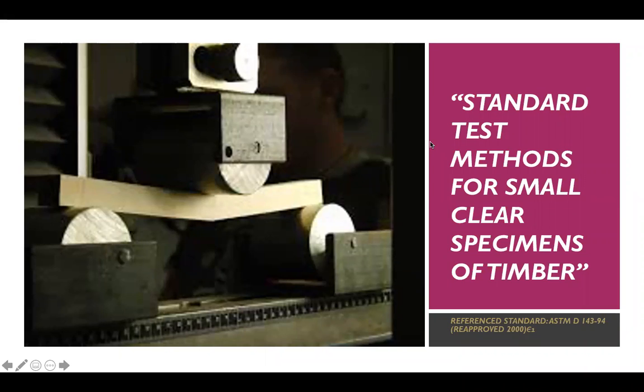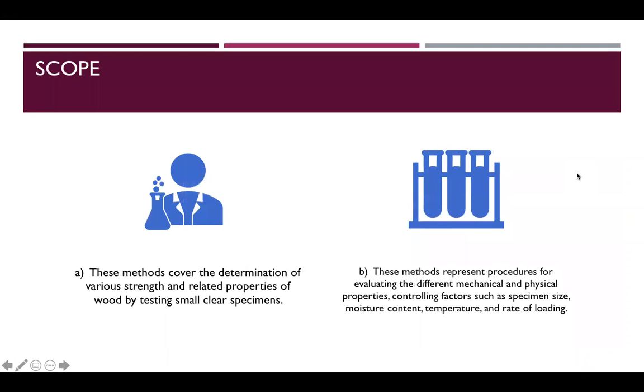So today I'm going to discuss the testing requirements for standard test methods for small clear specimens of timber. So the scope: these methods cover determination of various strength and related properties of wood by testing small clear specimens. And these methods represent the procedure for evaluating different mechanical and physical properties, controlling factors such as specimen size, moisture content, temperature, and rate of loading.